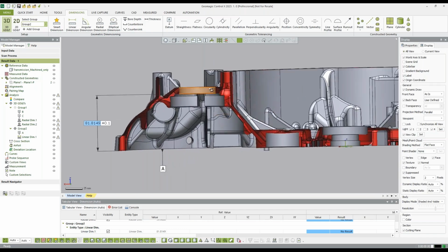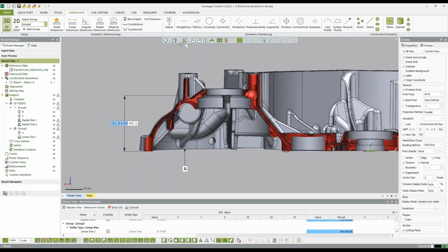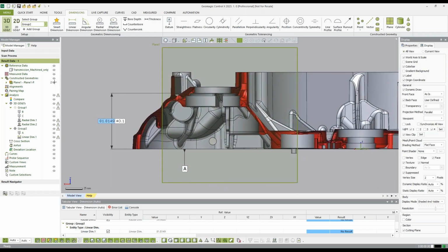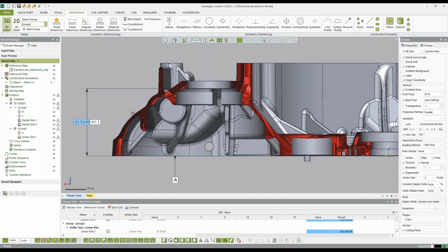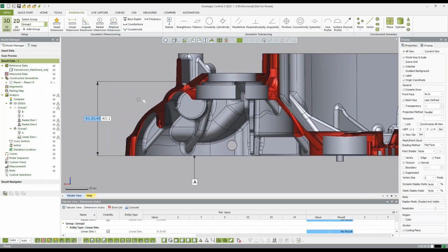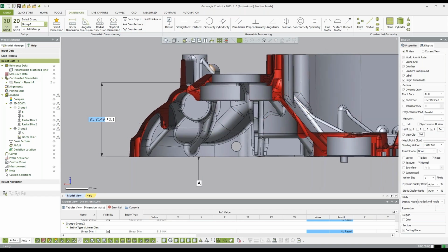And then we could come in and focus on this area if we want to. We could always go normal to that plane again if we want. I can come in and click that to lock us back in, which is again why I like to make the plane, because maybe that plane isn't on a standard view. And then if we just wanted to view a section, now I could do something with box and line something up to chop out the right side, but usually this works pretty well.